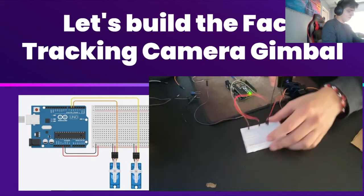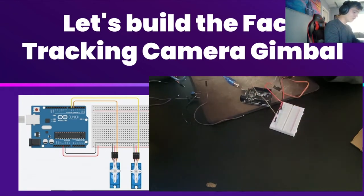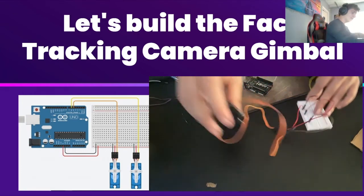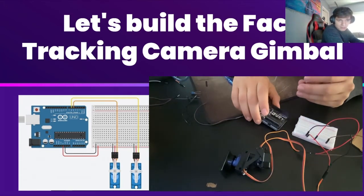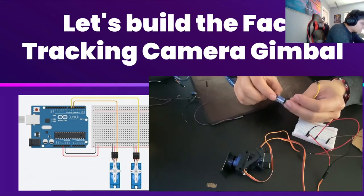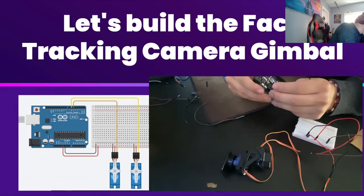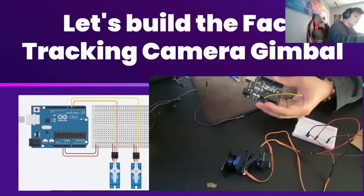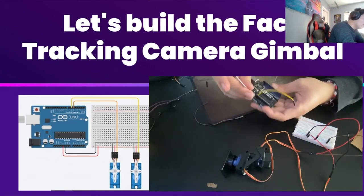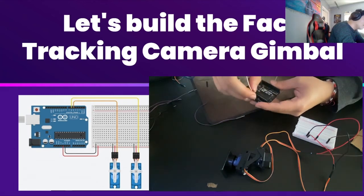So let's go ahead and disconnect the Arduino right now, because since we're connecting the wires, we don't want to have any issues with the electricity. Like in the presentation, we're going to go to the 5 volt, which is on the right side in this orientation, this one right here. It's going to be the 5th from the top. Then let's connect the ground wire as well, and we'll use a white wire for that. The ground is right under the 5 volt, so basically just under the 5 volt.